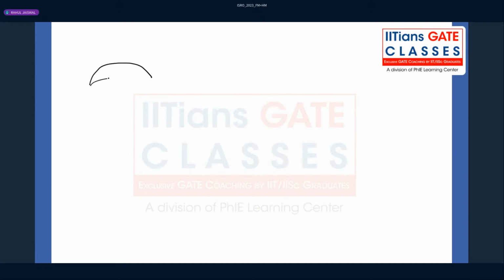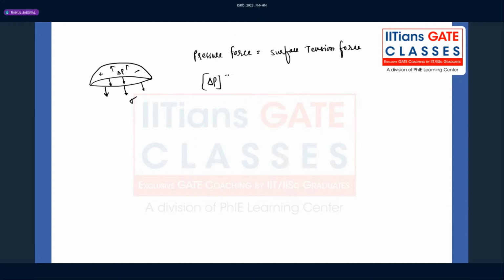Or we can take half of the liquid droplet, which is subjected to surface tension, and the droplet is subjected to the pressure, delta P. So now the bursting force, this pressure force, will be equal to the surface tension force. Bursting force will be delta P into pi by 4 d square.